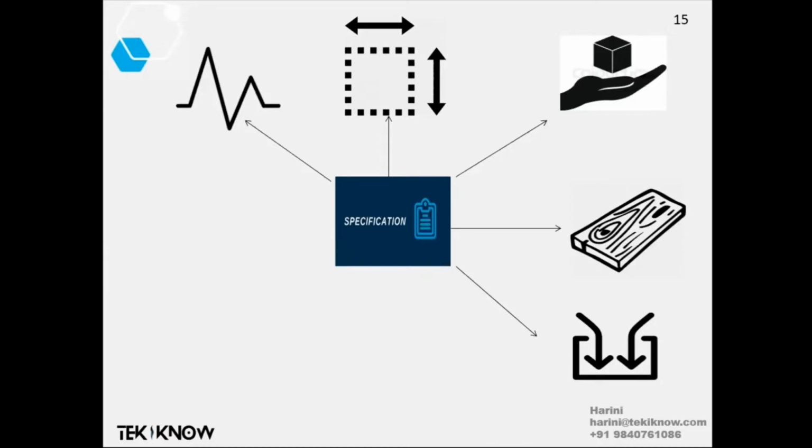I think people who studied antenna theory may know what the types of feeding available are. Otherwise, in the second session, you may have had a hands-on session on a patch antenna for millimeter wave, right? At that time you are giving some feed. I don't know what feed they are giving, maybe an inset feed or a simple strip line feed. That is a kind of feeding for a patch antenna. So you may select what kind of feeding, depending on where you are placing your antenna.